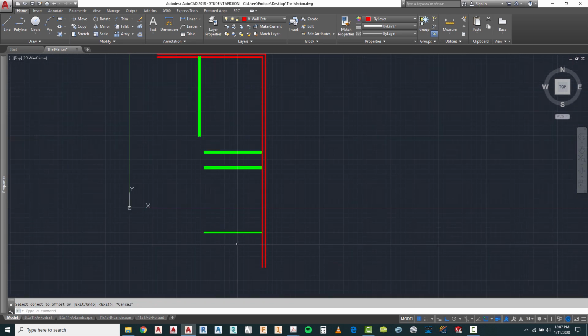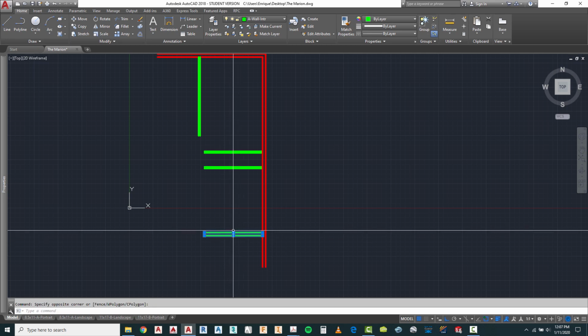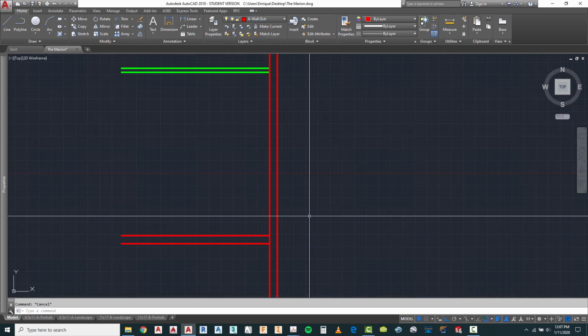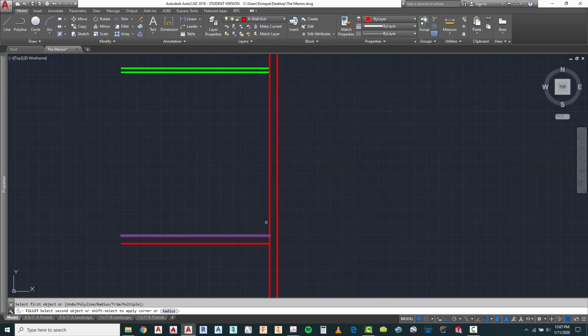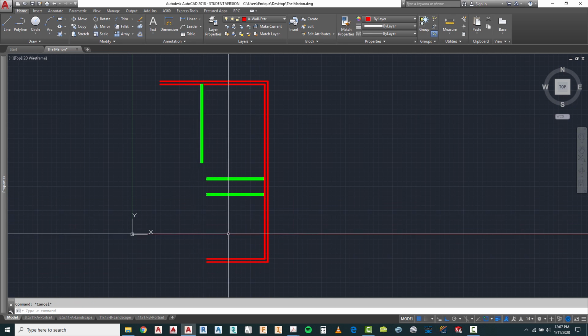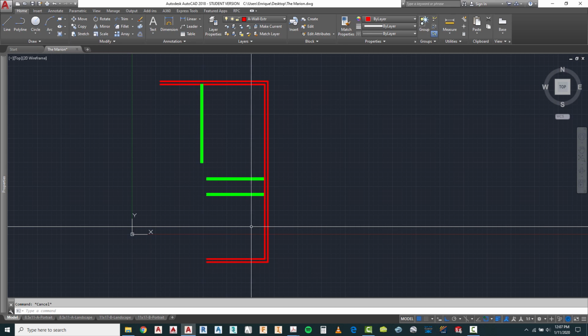And this now becomes an exterior wall. I'm going to offset it, the thickness of the exterior wall. I'm going to highlight it, change its layer to a wall exterior, and I'm going to use the fillet command right here. That, and now I can begin to work my way to the left in order to get the width of the room, which, if we remember, was 11 feet.